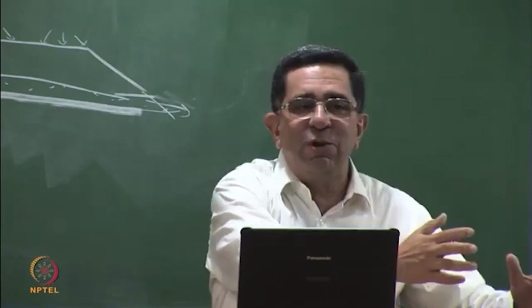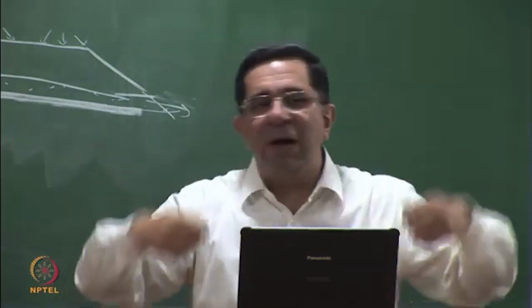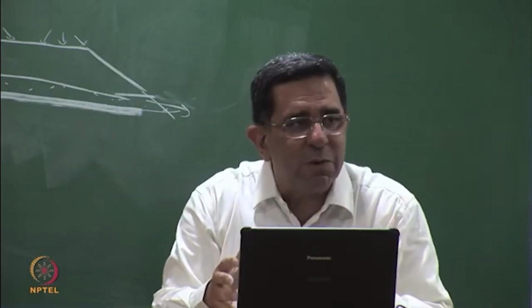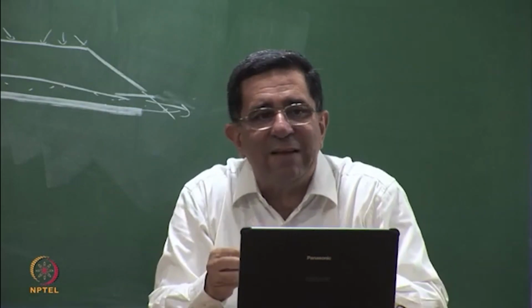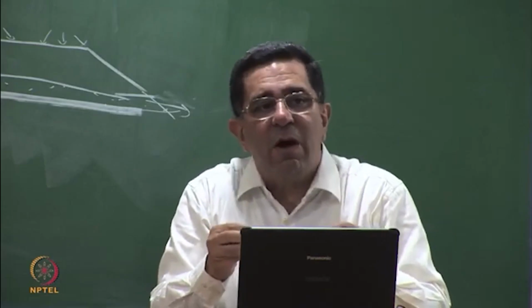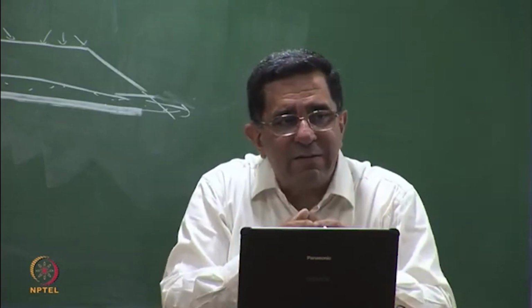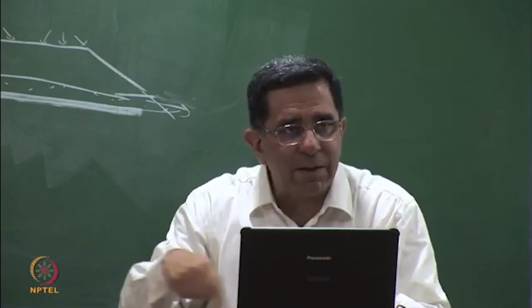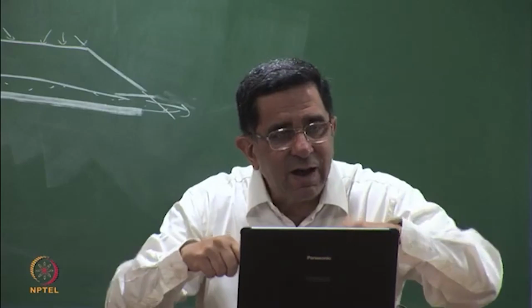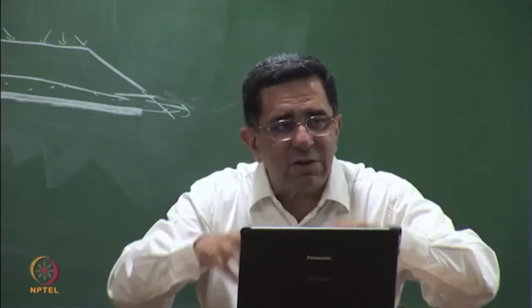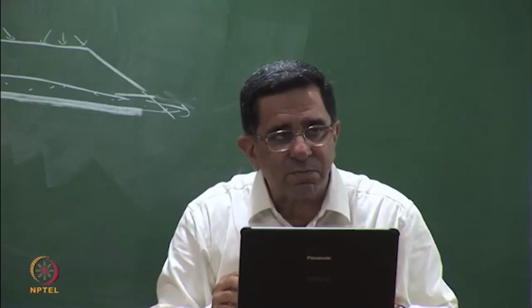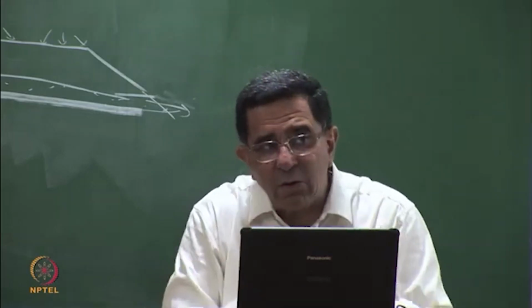It's not that one well is doing well, second well is doing well, and you will come back and say, sir, my water quality is fine, but the zone in between, which is not in the zone of influence, still has some stuff which is harmful. So our design is a dewatering design with the zone of influence overlapping. When I am injecting, I have to ensure that the injection liquid reaches everywhere into the ground. So that is our role.